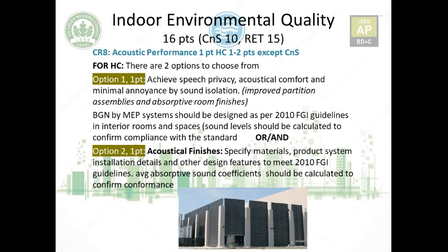The first one is to achieve speech privacy, which means you should have a private area where you can discuss confidential matters about the patient's illness and other private things, acoustical comfort, and minimal noise by sound isolation. So you have to isolate the sound from where you have all these things going on. How can it be done? By improved partition assemblies that have better STC ratings and absorptive room finishes.